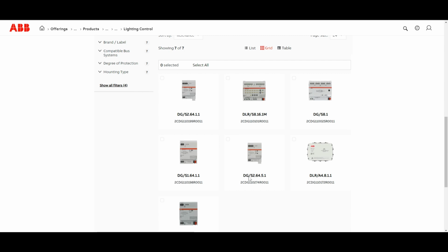These are really important, these options, and I think they're underutilized by a lot of manufacturers, and the reason for that is there's no actual programming for the DALI side or commissioning of the DALI network. And what it allows for is DALI lines that are switched together, so it's much easier for the installer. You just tell them to take the DALI cable to wherever the lights can be switched, and they're going to be switched in a group. So there's no actual addressing, there's no need for grouping or anything like that. It can make things a lot simpler, and when you weigh up the cost of what you're trying to do, this is a really cost-effective way to go because it's cheaper on the gateway and it's cheaper for your programming price.